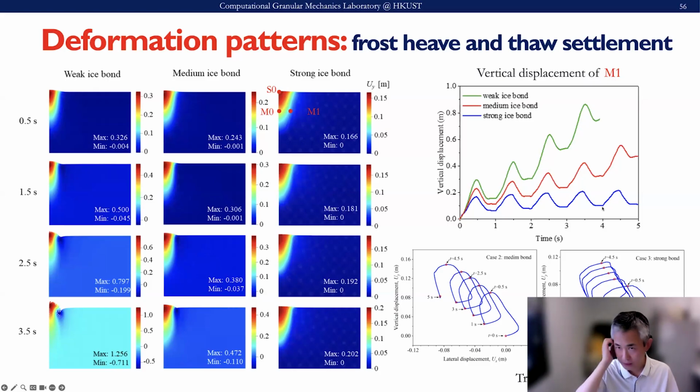This serves as a sensitivity study, and you can actually use that as a calibration process for real engineering problems here. Okay, and these are the cyclic loads, and the vertical displacement starts from this one and goes through these cycles, then goes up and generates a permanent trajectory and deformation here.